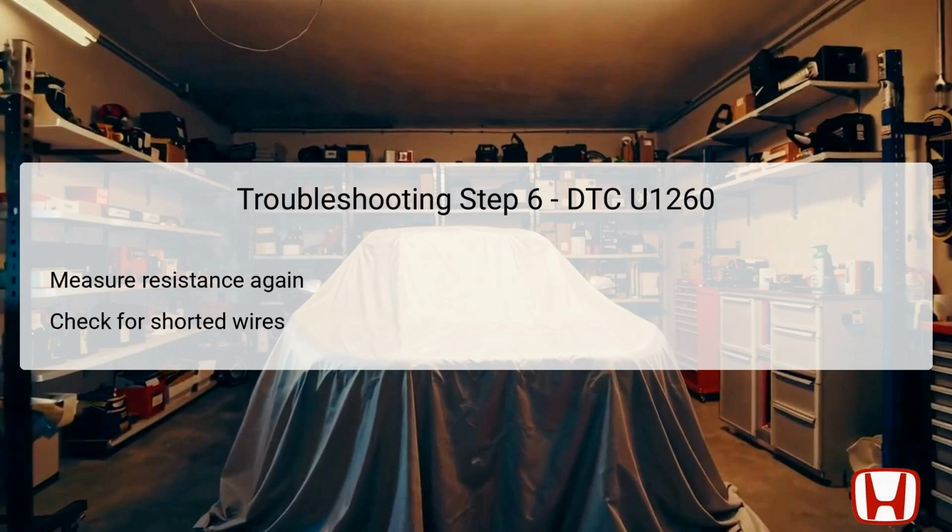In this 6th step, the technician continues to assess the integrity of the EOP-SIG line by measuring resistance between additional test points. As before, the vehicle must be in off mode, and both the auxiliary transmission fluid pump and TCM connectors must be disconnected. Resistance is evaluated between the auxiliary pump connector test point and body ground.